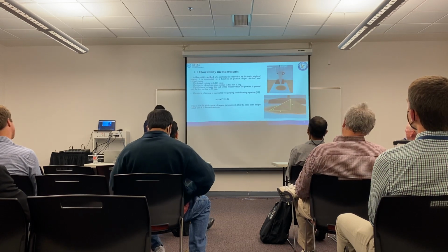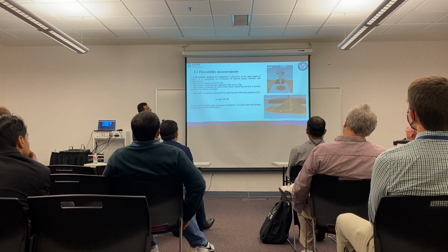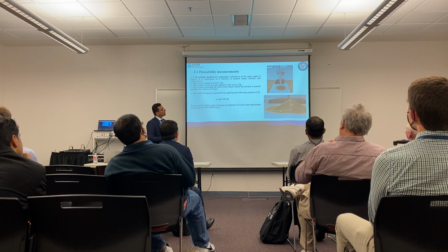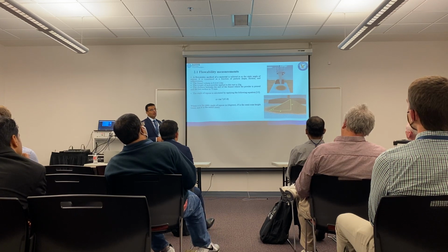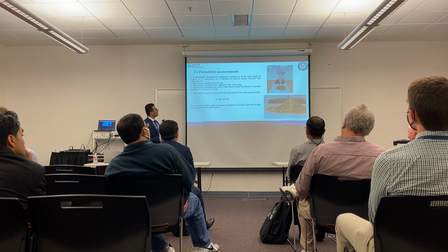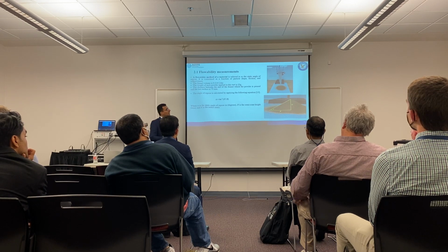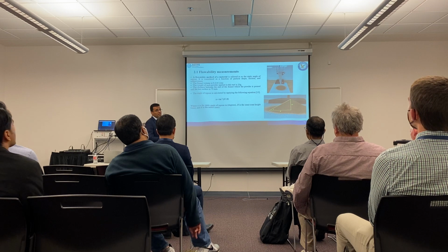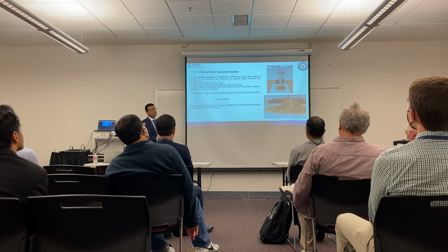Another physical property we measured is flowability. We installed this device using a funnel with a volume of 0.21 liter, and the distance between the end of this funnel and the test surface was 75 millimeters.